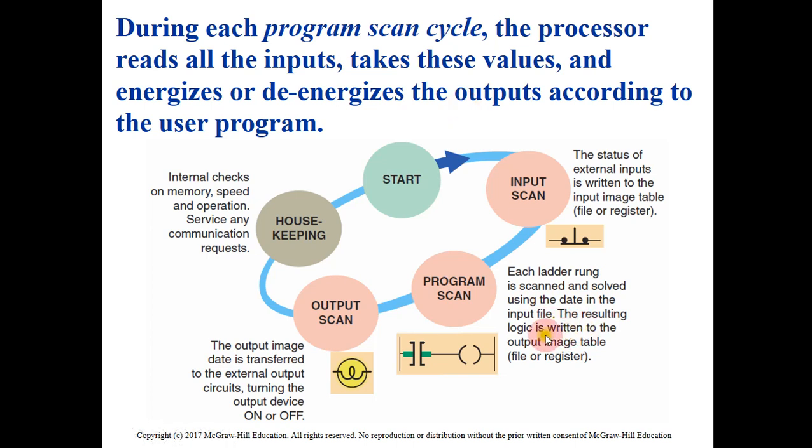The resulting logic will be written to the output image. Previously, in the previous video, we highlighted two types of image file: the input image table and the output image table. So after the processor scans the input and solves the software inside it, it will send the output to the output image table.